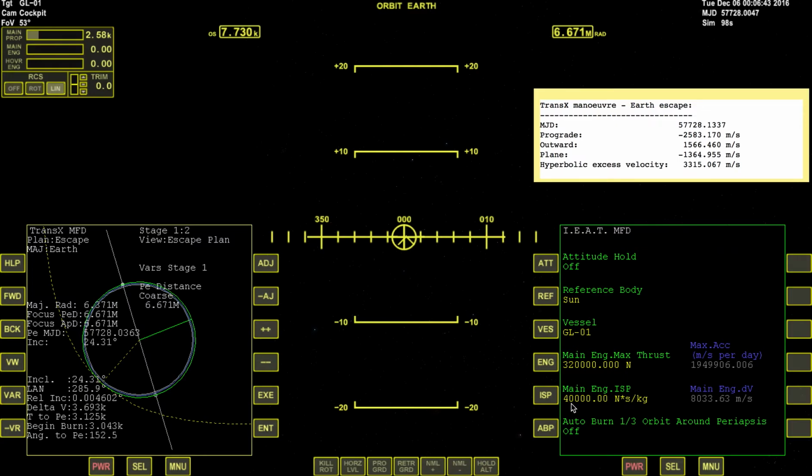So in the standard Delta Glider, it is assumed that the exhaust velocity of the mass, the stuff coming out the back end of the engines, is 40 kilometers a second, and that's roughly an order of magnitude too high for even the most powerful chemical rockets that we have at the moment.